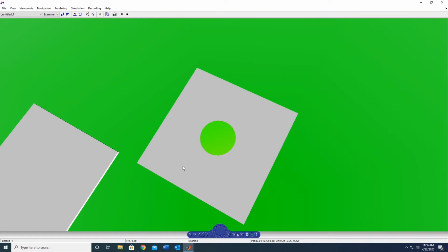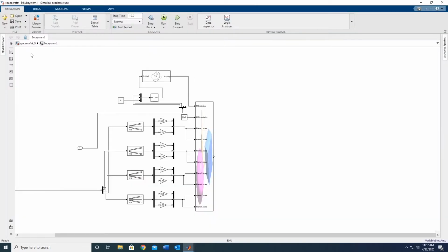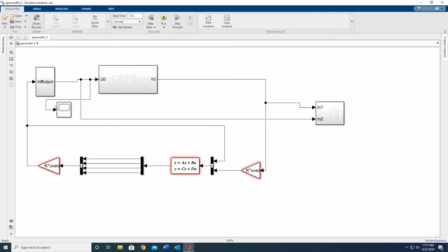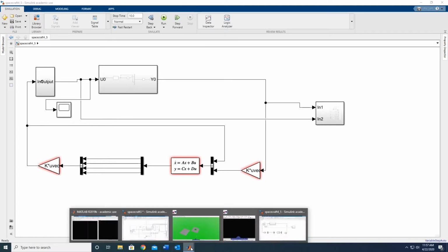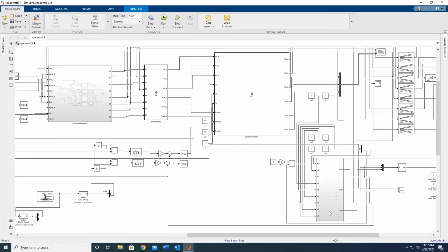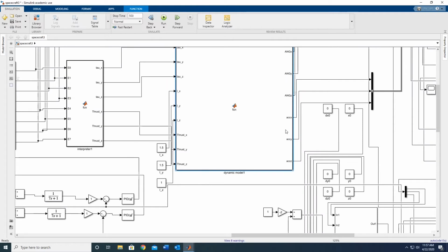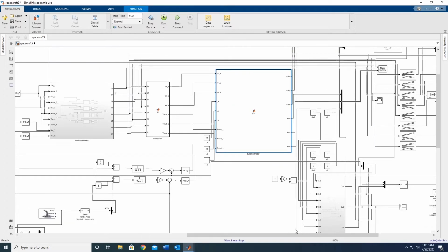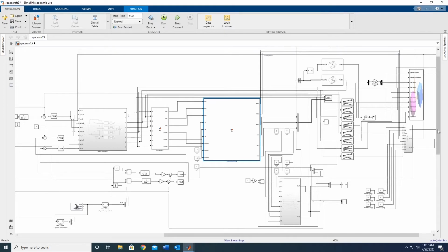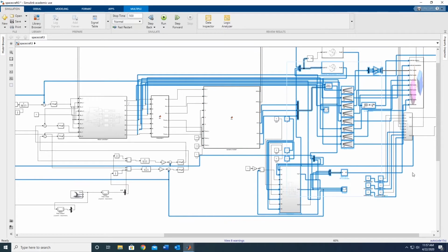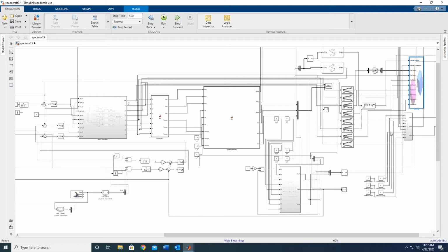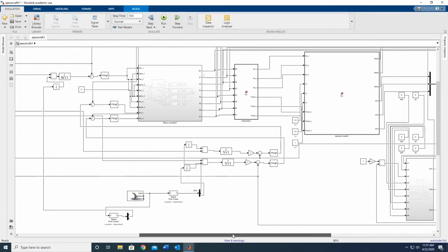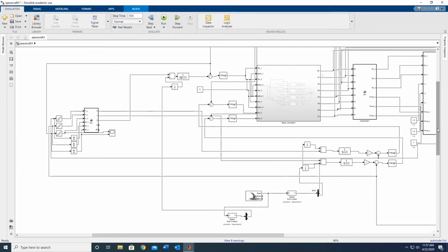All right, so how do we get there? This is a very similar system, but in state space. In this algorithm, I use a bunch of functions that I wrote to convert my thrust inputs into angular speeds, accelerations, and linear accelerations, sorry. And then I use just some integrators and some coordinate frame stitching to transfer those into some coordinates that I can output as an animation. I understand I'm going over this at a very high level. I haven't explained what any of this does, but just bear with me for now.